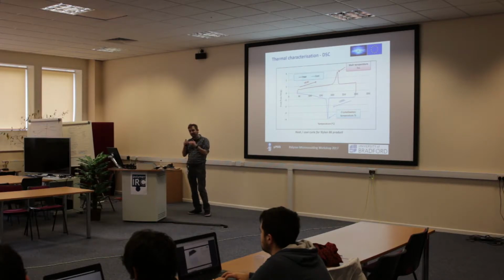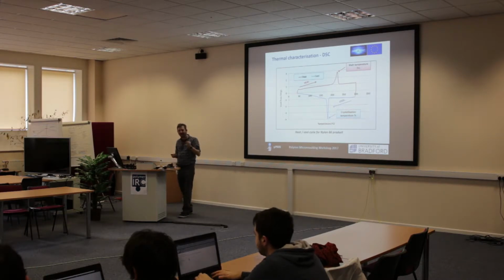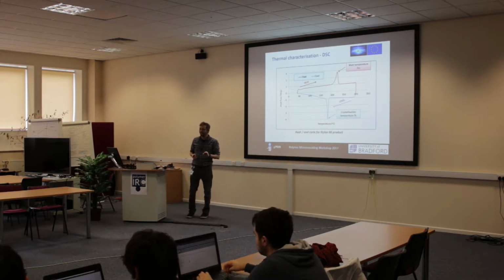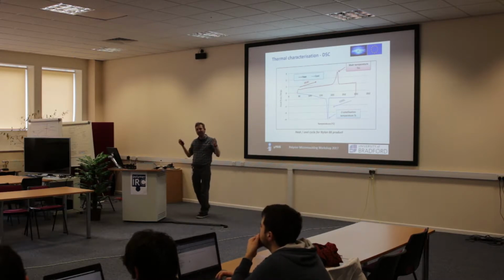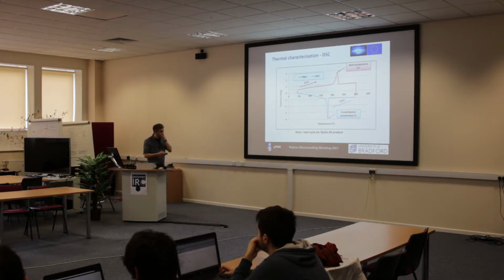So when people divide by this to give you a percentage crystallinity, it looks great on paper. However, what you're actually doing is taking your measurement, which is pure and good and nothing to do with the observer, and dividing it by a number that may well be wrong. Now, why would you ever do that? Why would you ever make your results less accurate than your results? You know what I mean? So it's something to be careful about.